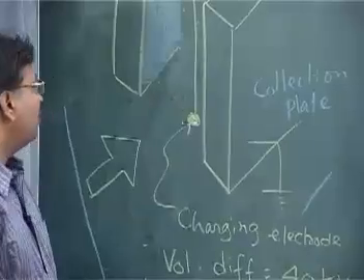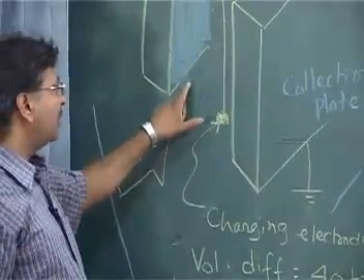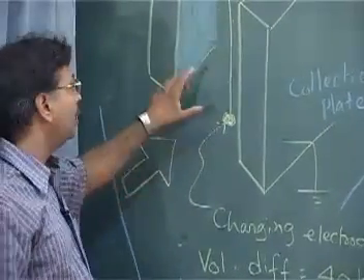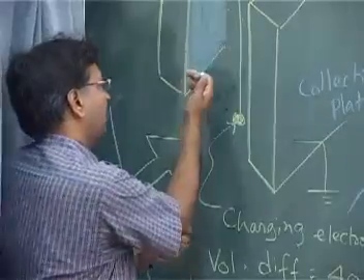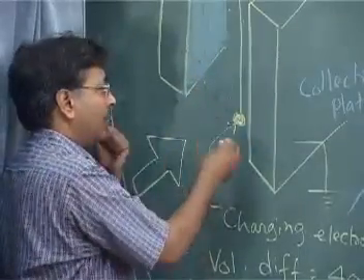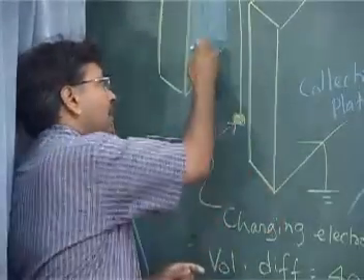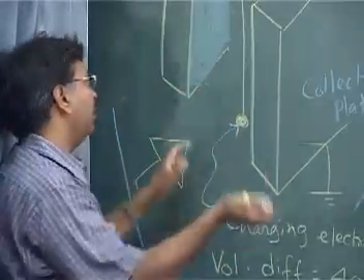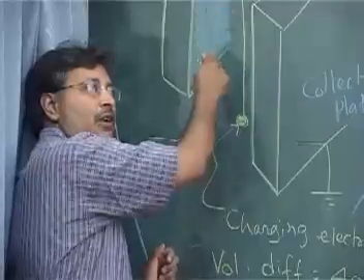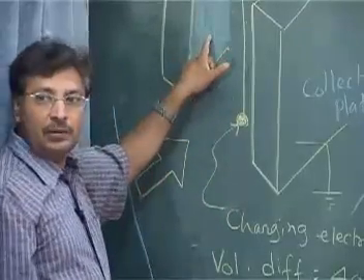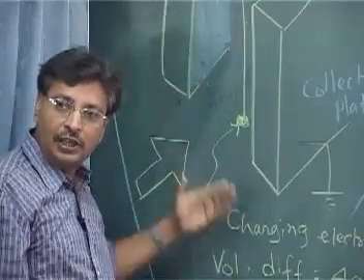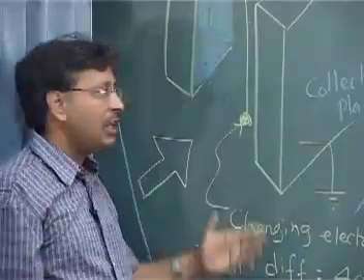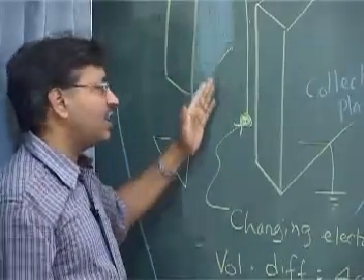What we do in the wrapping operation is, there is some kind of hammers, okay, which with some mechanical movement can come and hit the plate very hard, and then again they come and hit the plate, and once they hit the plate, the dust will fall in the hopper. Otherwise dust can be sticky and then it is not falling.